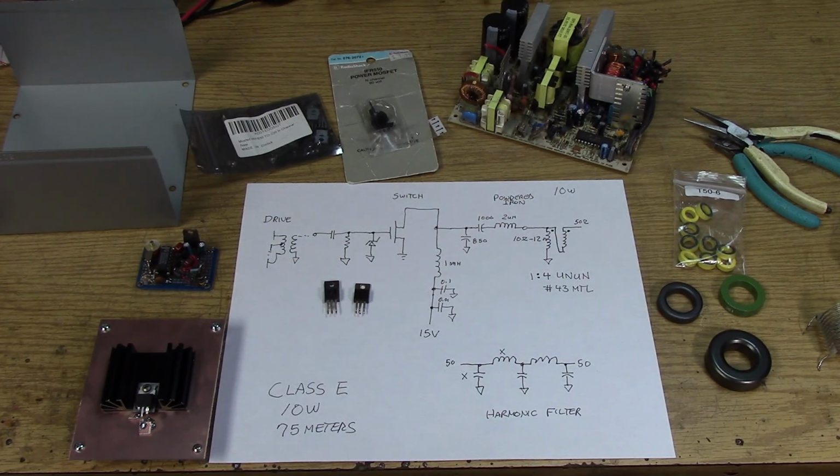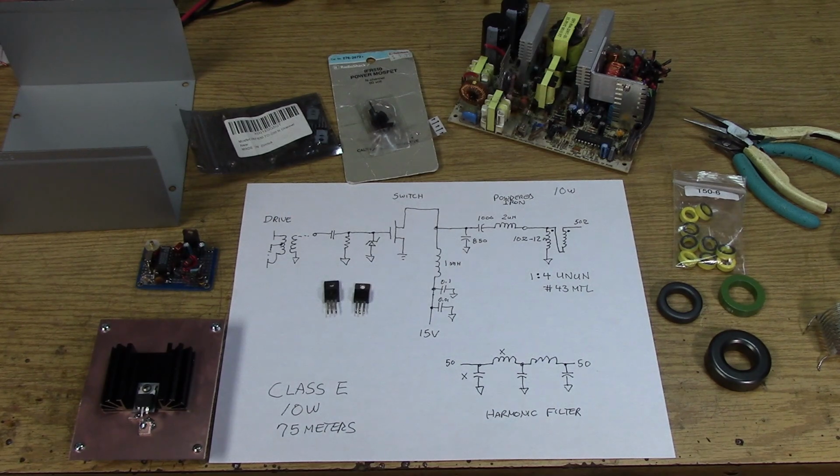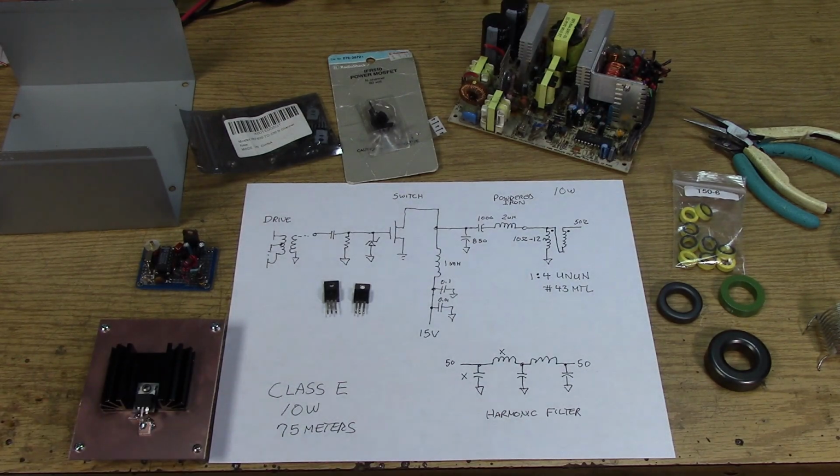We've found that today you're getting better efficiencies using MOSFETs, and pretty much the entire design industry has gone over to MOSFETs. And I'm not just talking about RF, I'm talking about switch mode power supplies, Class D audio amplifiers and such. These are all using MOSFETs today, whereas high-speed switching bipolar power transistors were used from probably the 70s up through the mid-2000s. And we are going to try a bipolar transistor out of an ATX power supply. Let's see if we can get Class E with bipolar.